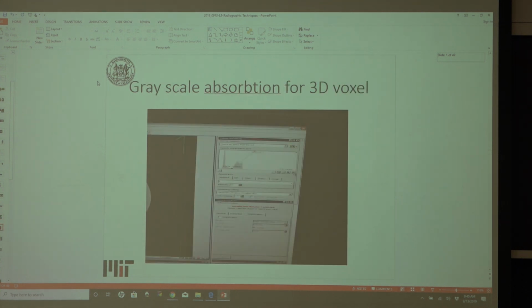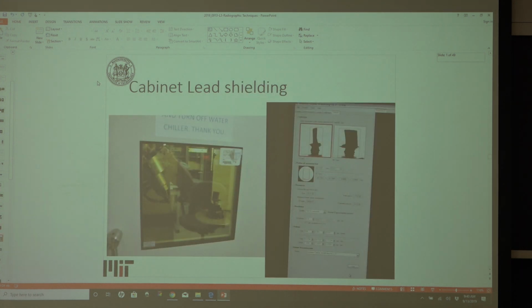One of the things that has a great effect on the output is where you decide to put that dynamic range. That is basically an option that a user has to select, and that deals with how many grayscale images and the differentiation and the gradients between the grayscales. If you don't do it properly at the beginning of the test, all you're going to get on the output is a black image.